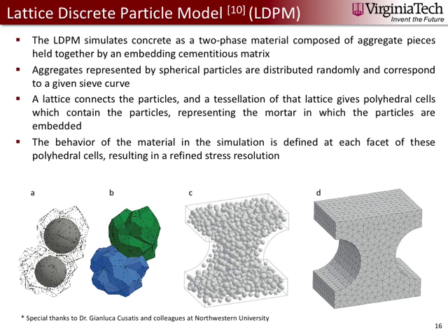The lattice discrete particle model has been developed by Dr. Gianluca Cusatis at Northwestern University, and it simulates concrete as a two-phase material. The aggregate pieces are simulated as spherical particles distributed randomly throughout the member, and a lattice connects these particles. A tessellation of this lattice results in polyhedral cells which contain the particles. You can see an example of that on the bottom left here. And these polyhedral cells represent the matrix in which aggregate particles are embedded in real concrete.